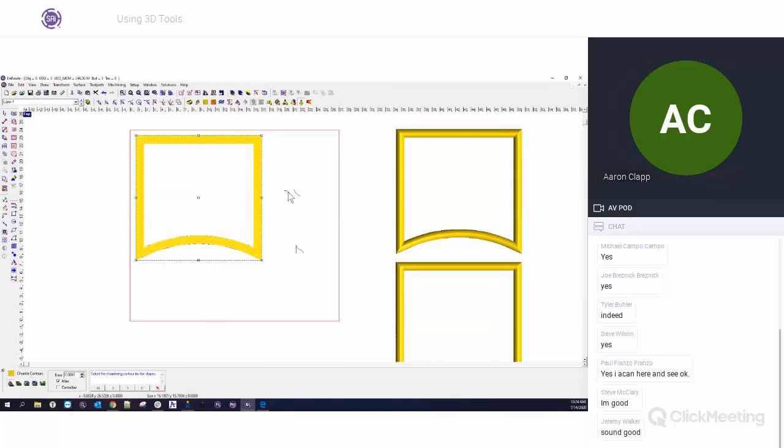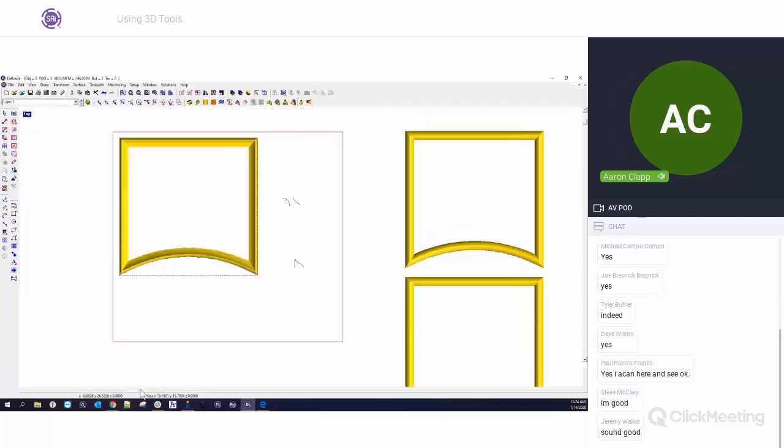Select this shape here. So select the chamfering contour for the shapes. The first one is always for the outside. So along this outside edge, right here, click there. I hit next, and now it says select the chamfering contour for the holes. That's going to be for the inside. Technically, this big white space in here, this is your hole. And so I'm going to click here. Now that one highlights red, and now we hit apply.